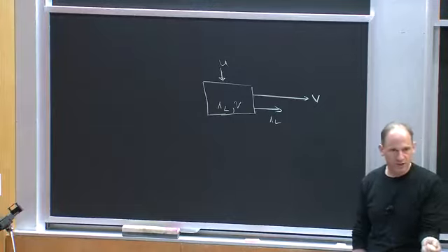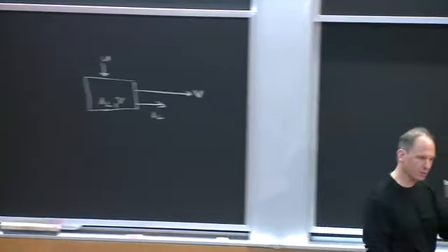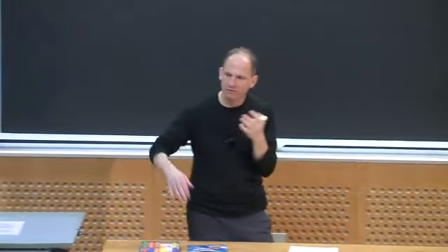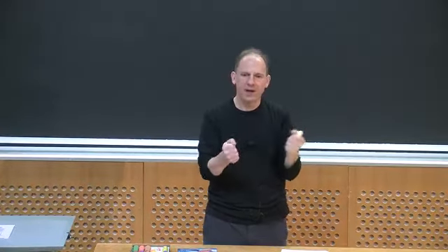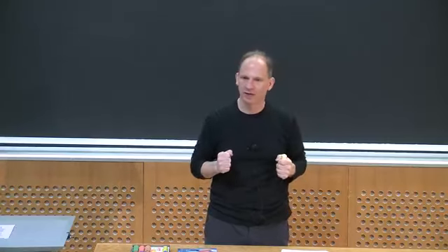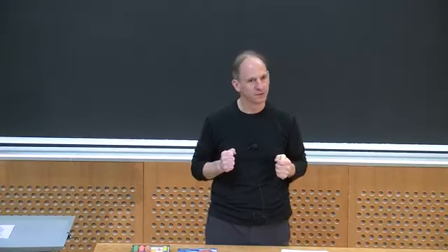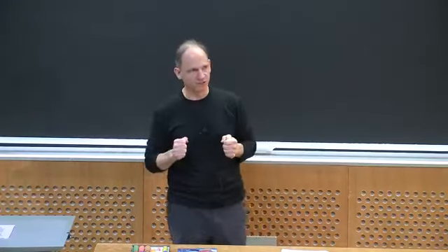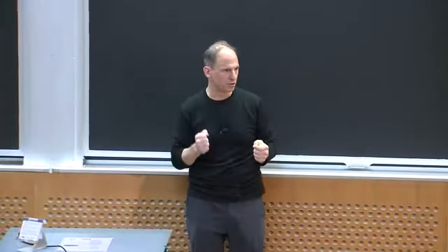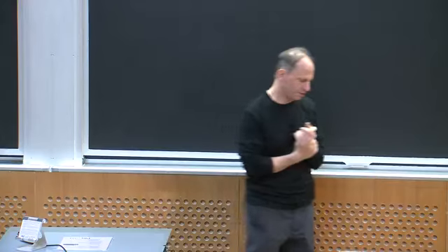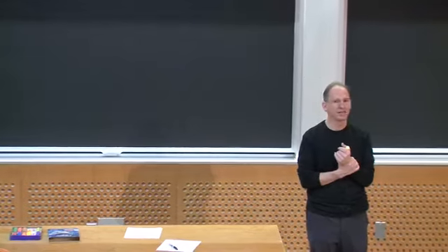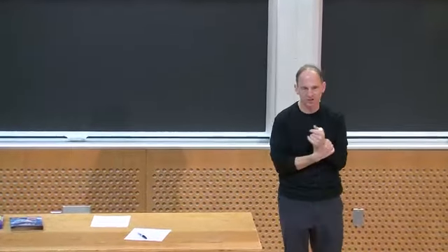What a control person would tell you is, if you're not happy with your dynamics and you have a controllable system, feed back all of your states. Do full state feedback. If you feed back all of your states, you can place your dynamics much better. And we're going to do a version of that called current mode control. The general concept originated in the 1960s. The version I'm going to tell you about came about in the late 1970s, and there's lots of versions of this idea.